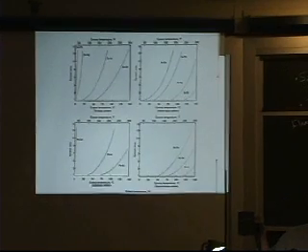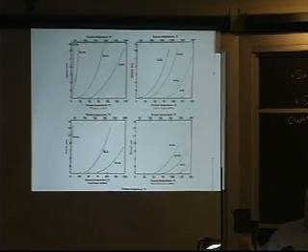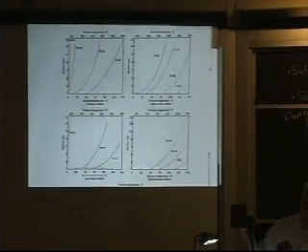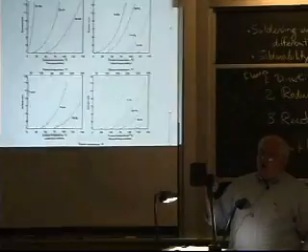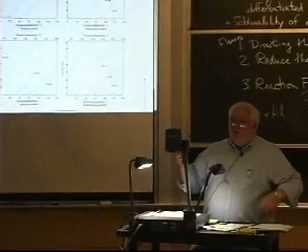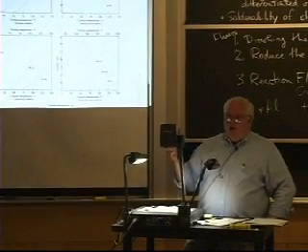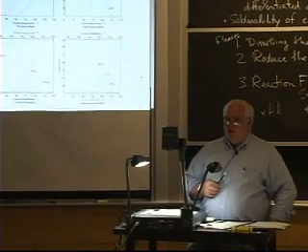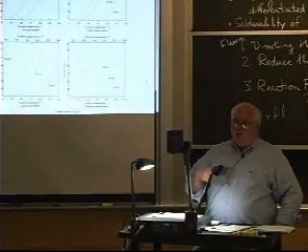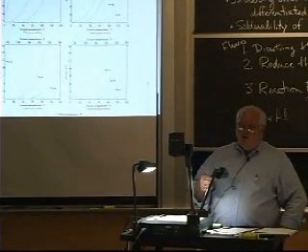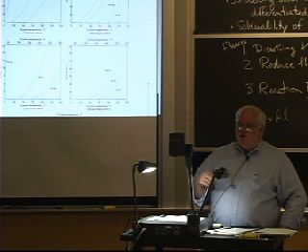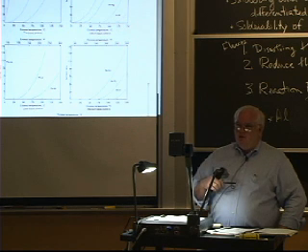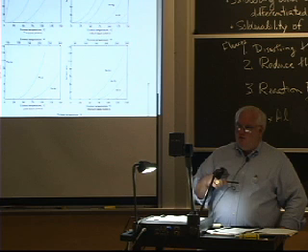There's a situation of a gold mine in Canada where the incoming water, actually it's arsenic, not lead, but the natural arsenic in this river in the wilds of Alaska is like 7 parts per million. They use that water for the gold mining operation, and the EPA requires them to have less than 1 part per million arsenic in the water that they put back into the river.